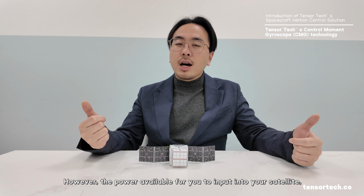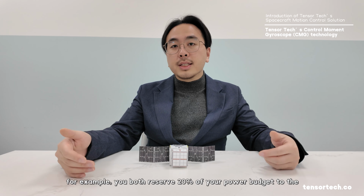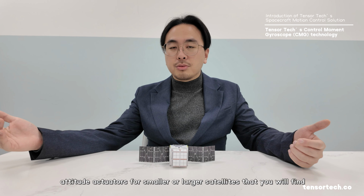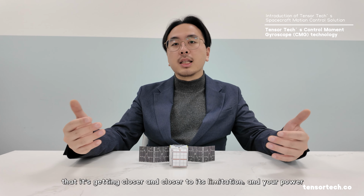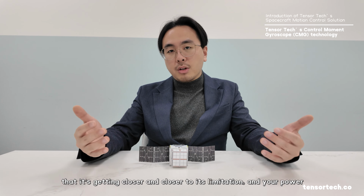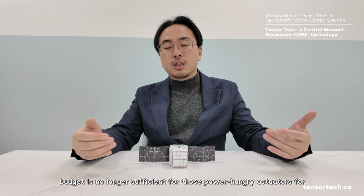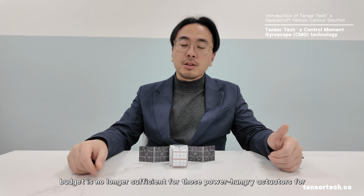However, the power available to input into your satellite is limited. For example, you may reserve 20% of your power budget for the attitude actuators on a smaller or larger satellite, but you will find that it gets closer and closer to its limitation, and your power budget is no longer sufficient for those power-hungry actuators.